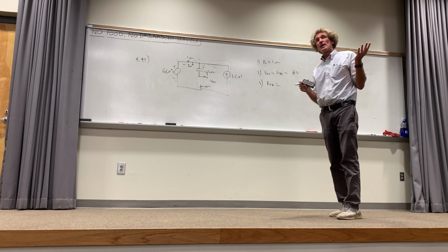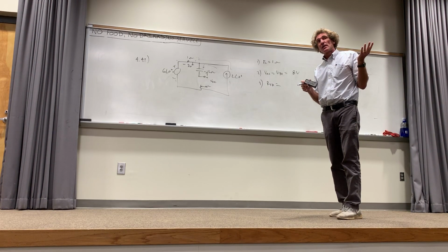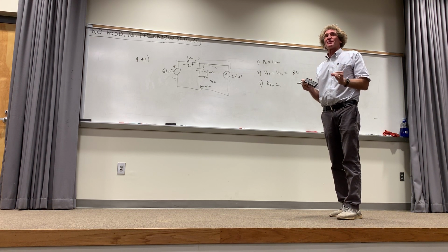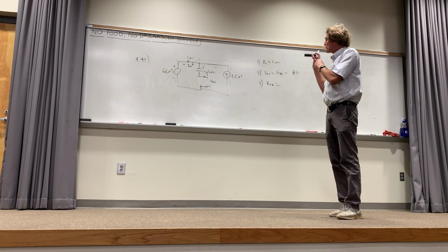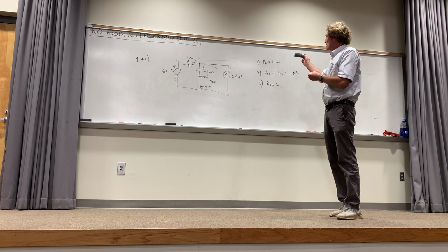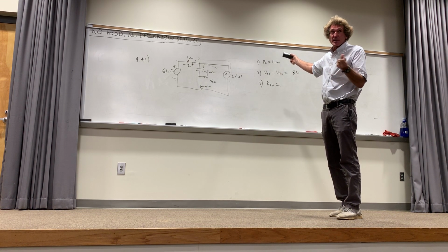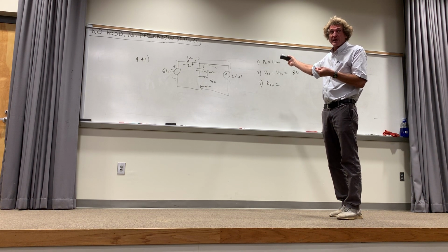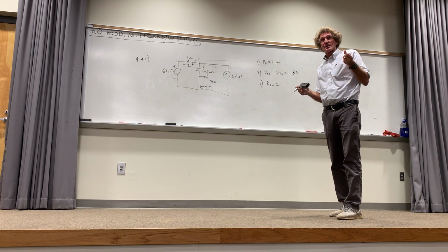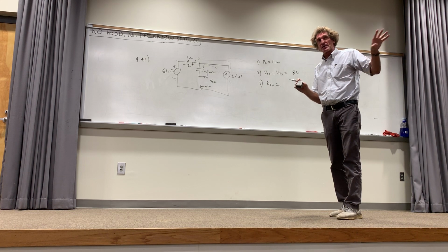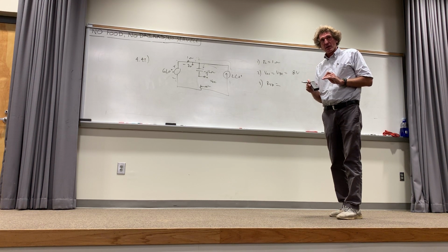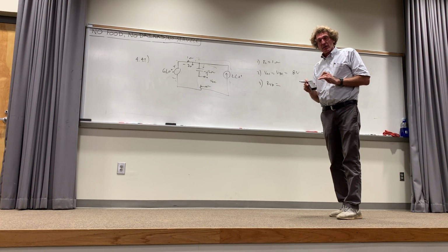Yes, sir. So do we treat this any differently than mesh analysis? Well, remember, we're doing Thevenin. It's completely different because with Thevenin, you first identify the load. You're not summing voltages around a closed loop and setting them equal to 0. What you're doing is finding the voltage across the open circuit. So there's no summing around a closed loop and setting it equal to 0. That's mesh.